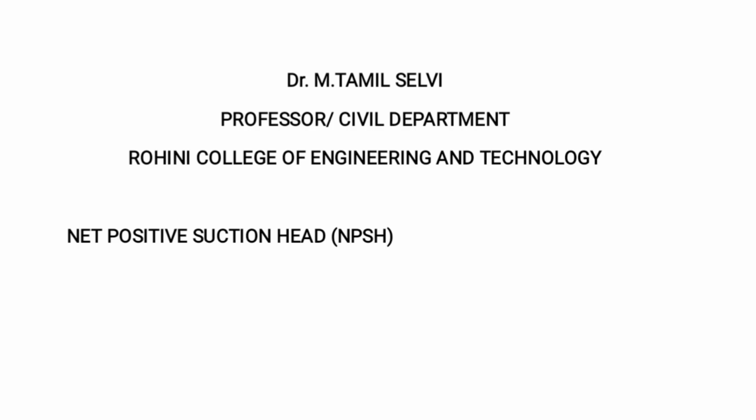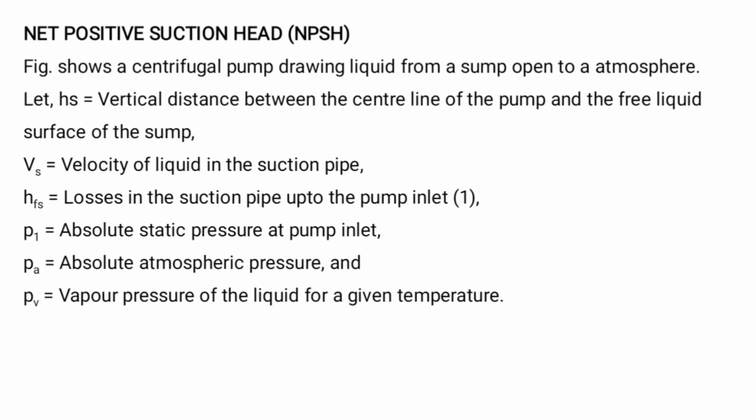Net positive suction head. Net positive suction head is otherwise called NPSH. In this centrifugal pump, drawing liquid from a sump open to atmosphere, Hs is equal to the vertical distance between the center line of the pump and the free liquid surface of the pump. Hs is the suction head.